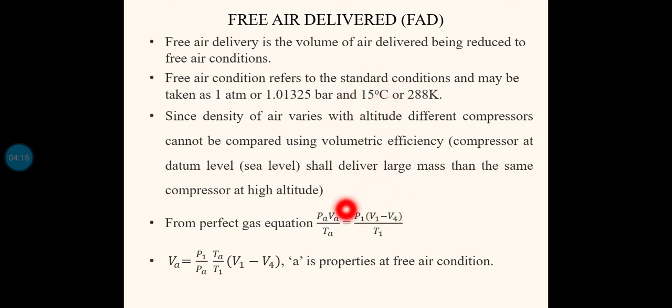These values correspond to the suction condition of the air, or entry condition of the air into the cylinder. P1 corresponds to the pressure of the air actually entering into the cylinder. V1 minus V4 is the actual swept volume, considering the clearance volume.